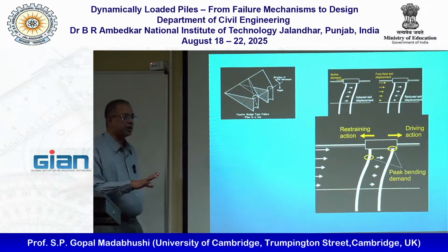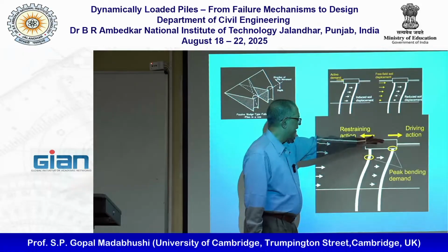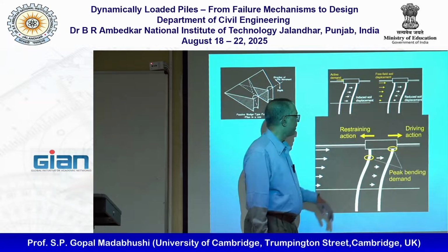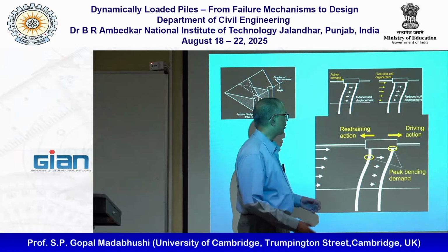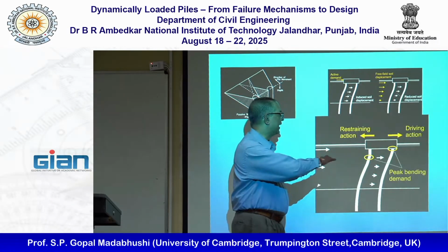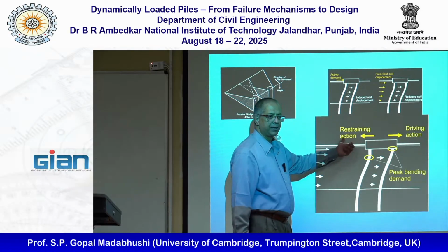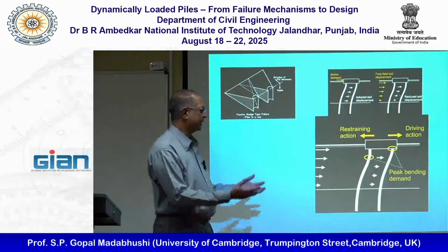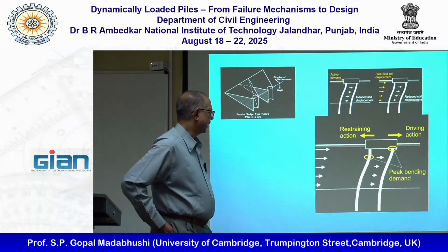Also, we talked about formation of these hinges. So we do get the peak bending moments somewhere like that, which we looked at yesterday. Effectively, the New Zealand code talks about restraining action and driving action. So the earthquake creates the driving action and the structural stiffness provides the restraint. It's like a frame action, right? Basically a pile group with a pile cap is like a frame.